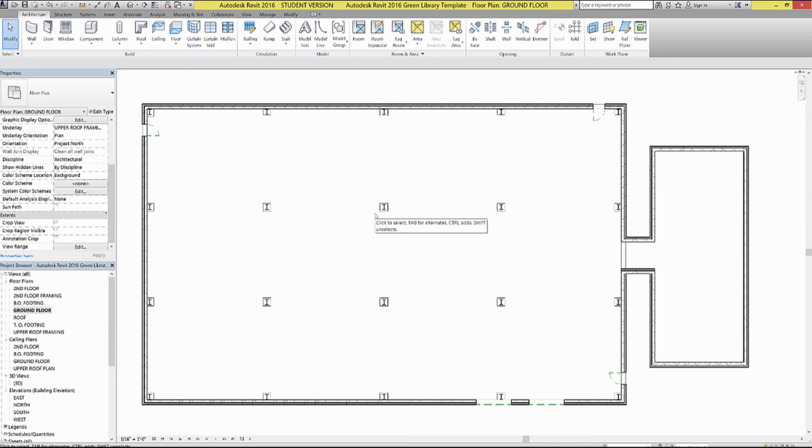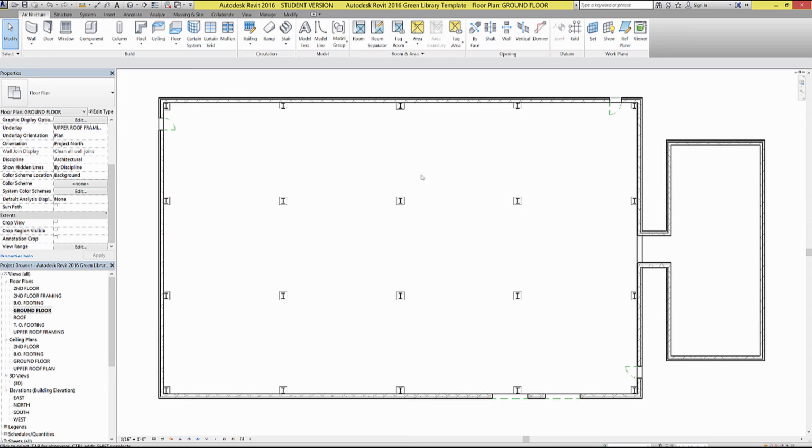For the habitat project, we kind of skipped past this step, and it's actually really important because we can't make a room schedule unless we set the area plan in advance. So you might remember we did a window schedule and a door schedule, but we had to skip on the room schedule. But not this time. This time we add it.